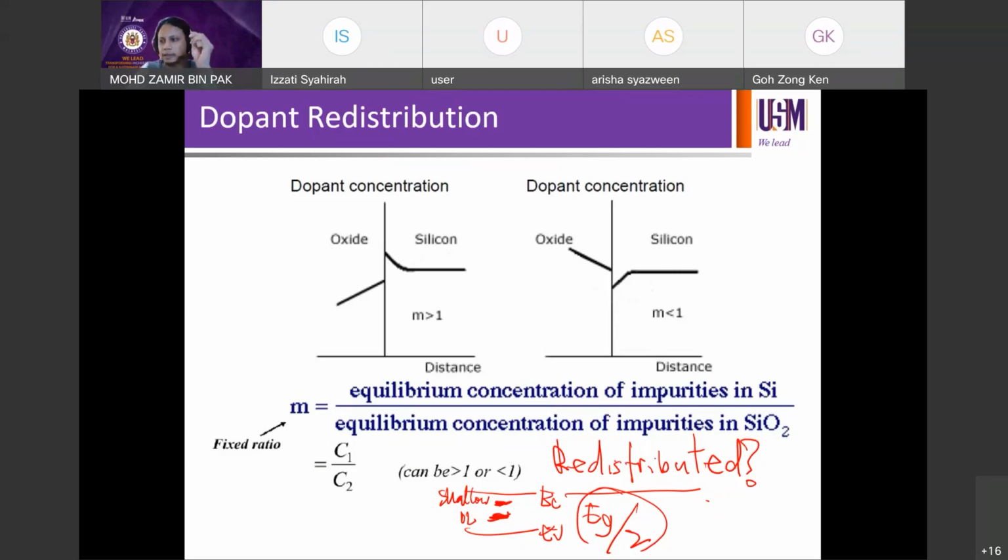Say you have metal on your silicon wafer, and just imagine you have metals on the surface, then you can probably wash off the metals. But if the metal is already on the surface, and the next step is a high temperature step, then whatever metals you have on the surface will be driven into silicon, will be diffused into silicon. They can migrate in silicon and